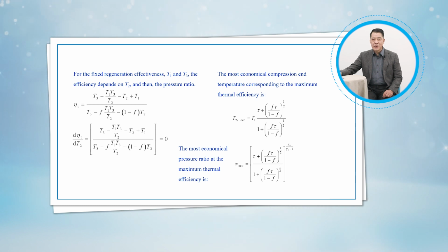The actual gas turbine cycle differs from the ideal Brayton cycle on several accounts. For one thing, some pressure drop during the heat addition and heat rejection process is inevitable. More importantly, the actual work input to the compressor is more, and the actual work output from the turbine is less because of irreversibilities.